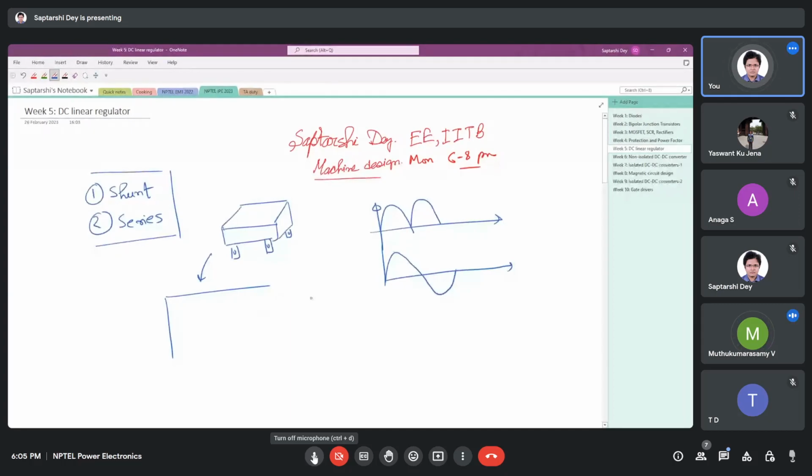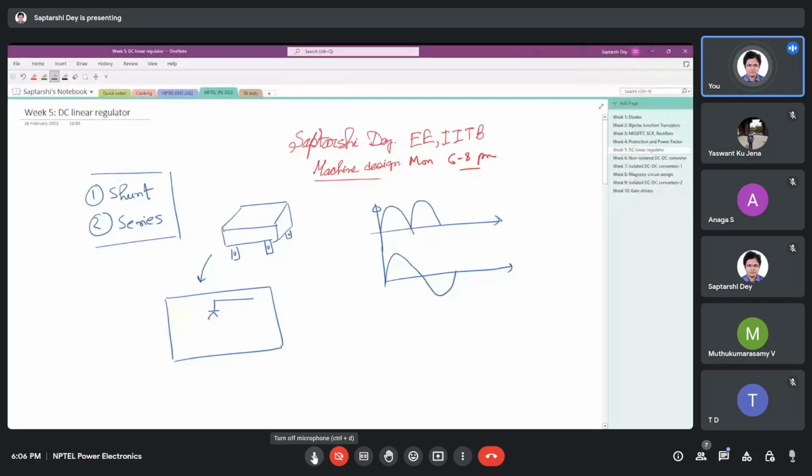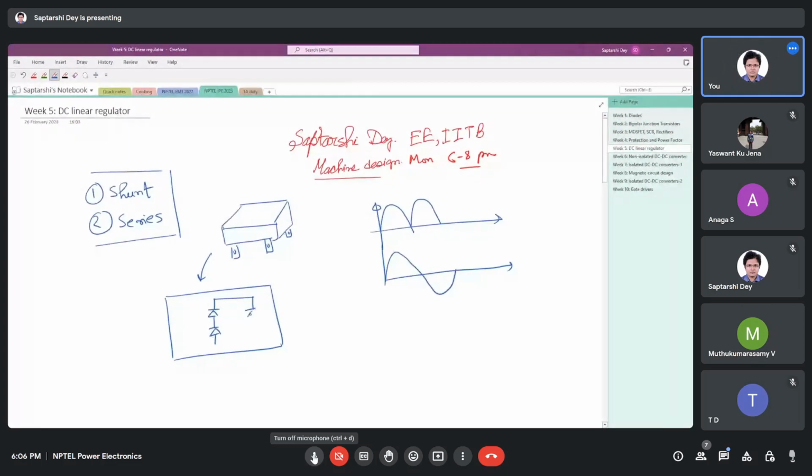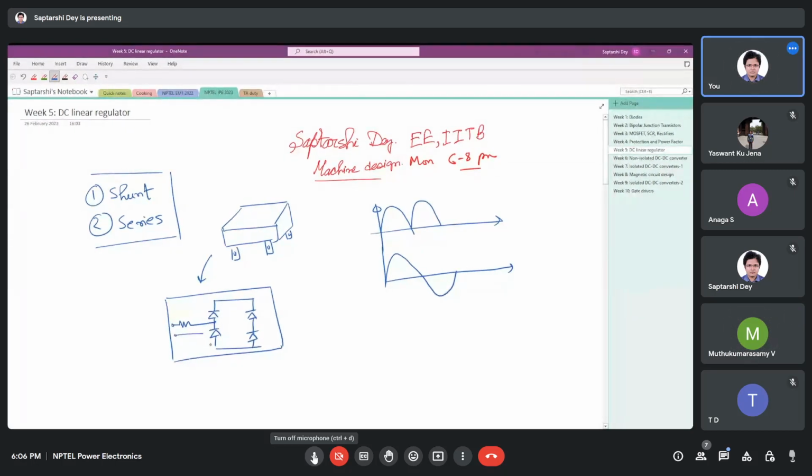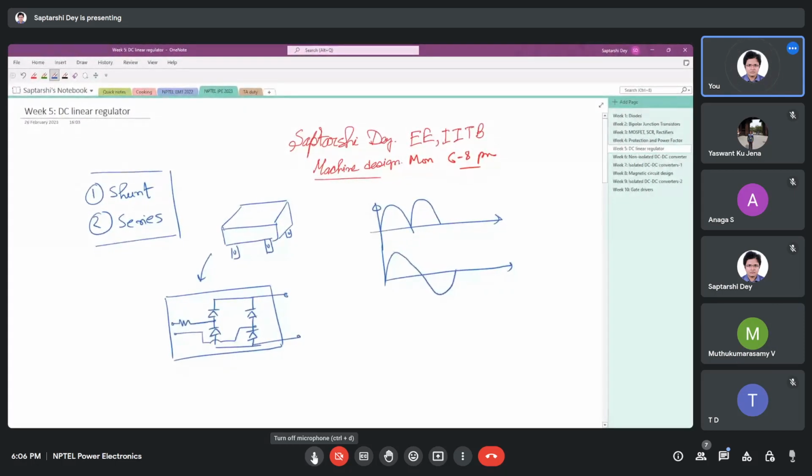When the manufacturers are making the rectifier, they do not know how you are going to use it, what kind of load you are going to connect. They also don't know whether you are going to connect any resistance or not for inrush limiting. Maybe they are adding this. I'm just saying, not necessarily. But the idea is this has been given to make your calculation easy. But yes, if there is no capacitor outside, there will be no inrush current.